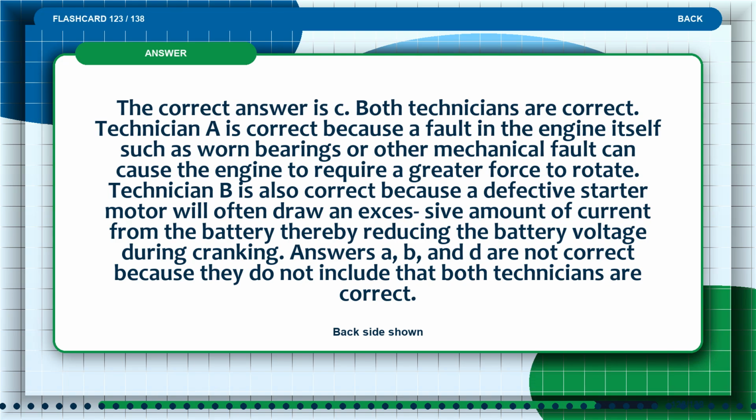The answer is. The correct answer is C. Both technicians are correct. Technician A is correct because a fault in the engine itself, such as worn bearings or other mechanical fault, can cause the engine to require a greater force to rotate.